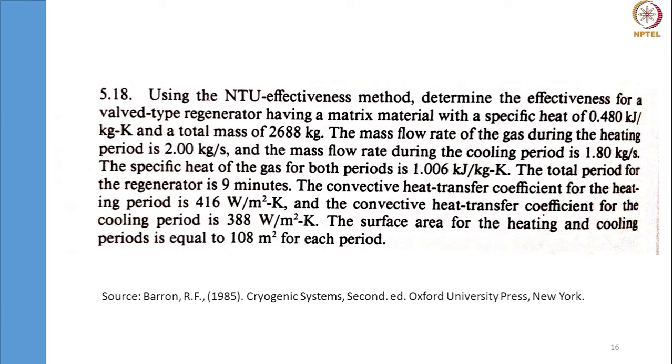We can also check one of the worked out problems in R.K. Shah's textbook, and also in Barron there was one more exercise problem, just after this, 5.17 or 5.18, where he also advises to use the lambda pi method, or else we can go for the effectiveness NTU method also. Both will give the same final answer.